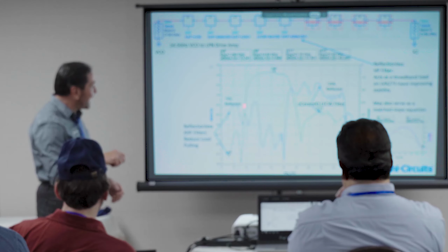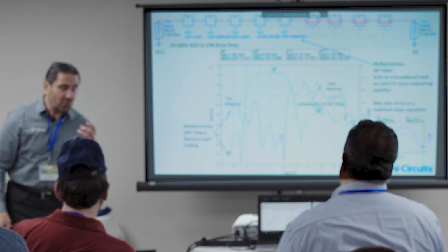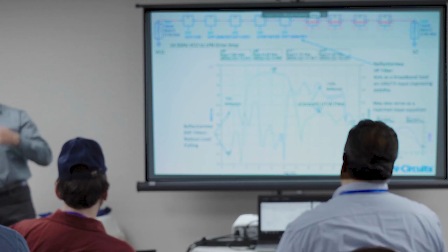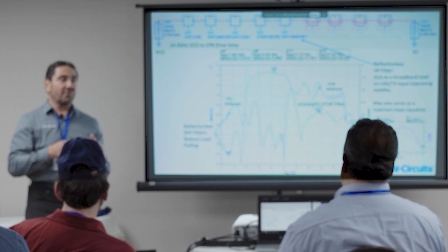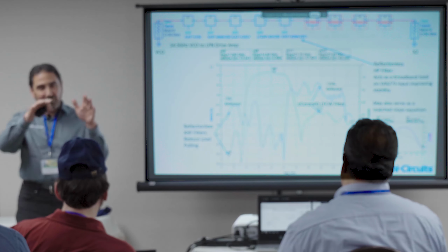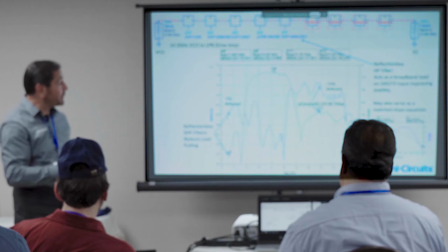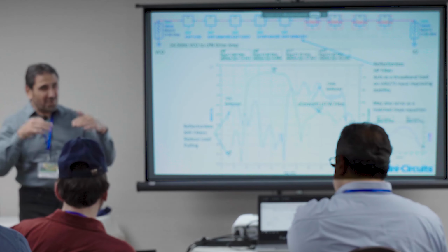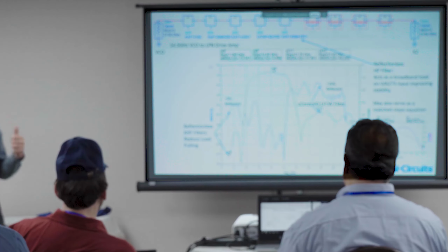We come into the pass band of both the high pass and then the Micro Ceramic low pass. The Micro Ceramics are going to have much better rejection, much closer in. The reflectionless ones tend to have a little bit wider reject band. The Micro Ceramic filters are very sharp. So that's why we used it here, because those spurs are much lower. I'm not as worried about reflecting that power back into the VCO.